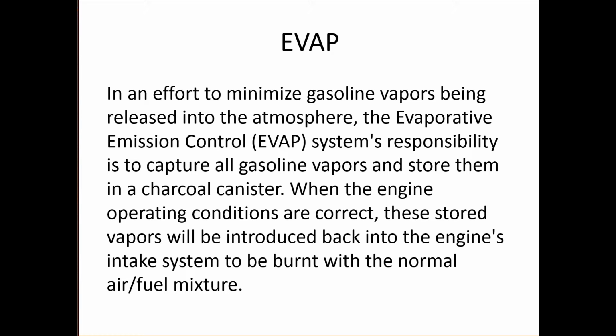As the car is moving, gasoline in the gas tank is producing vapors. When you fuel the car, it produces vapors, and as the fuel pump is cycling fuel through the fuel rail for the injectors and back to the tank, for some systems, other systems are localized, either internal to the tank or between the fuel filter, but nonetheless fuel is being moved around, and that's going to produce vapors. In older cars before 96, not all, some of that vapor was released to the atmosphere, and that's not good. That's pure hydrocarbons, and it's not good for the environment.